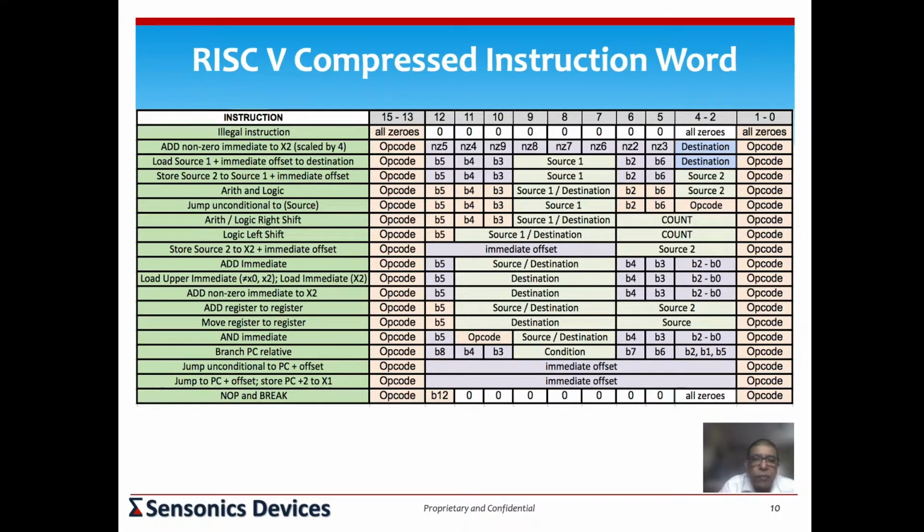So here is a similar summary for the compressed instruction word. The compressed instruction is a subset of the 32-bit instruction, excepting that this is 16 wide. And as you can see here, even here, the opcodes have been maintained orthogonal. The peach color, as before, is the opcode color. So those bits in the various instructions are meant for opcode. And as you can see here, the opcodes are also largely orthogonal. But there are many more instruction types called out uniquely here.